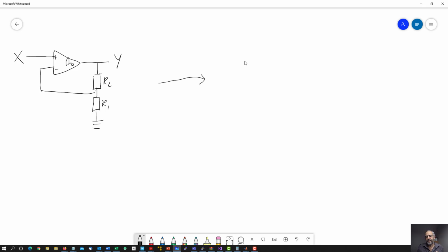Or in other words, this diagram that we have here on the left is not something you can enter in MATLAB Simulink, because we don't have an op-amp in Simulink, and we don't have this voltage divider and resistors and ground value and so on. So we have to redraw that diagram in such a way that it could be entered in MATLAB. Then it's a process diagram.